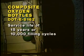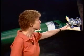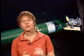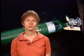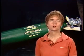Now, how do you determine how much oxygen you've got in a portable high-pressure cylinder? Well, the easy way when you're working with a portable cylinder is to simply read the pressure gauge that is mounted on the cylinder. You want to make sure that it always has some pressure in it, because if oxygen bottle pressure is allowed to drop below a specified minimum, moisture can collect in the bottle, and that can result in corrosion and some other problems.